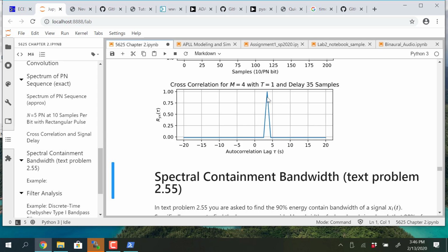But in a multipath situation, we could put in more, and then there'd be more peaks. There might be a precursor because there might be something near which doesn't reflect strongly, and then there might be some more, smaller peaks afterwards, which would be the multipath.